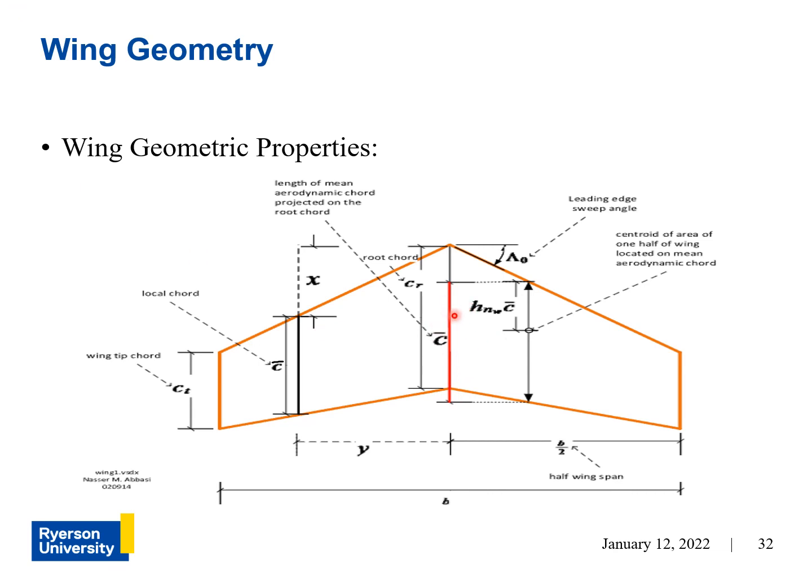That means the aerodynamic center of the mean aerodynamic chord would be somewhere here. And if you know that location with respect to the center of gravity, you have your pitching moment of the whole wing, right? Once you have that information, you can calculate the size of your tail and the boom to be able to counter that pitching moment to trim your aircraft. So that's why it's important to know the mean aerodynamic chord.